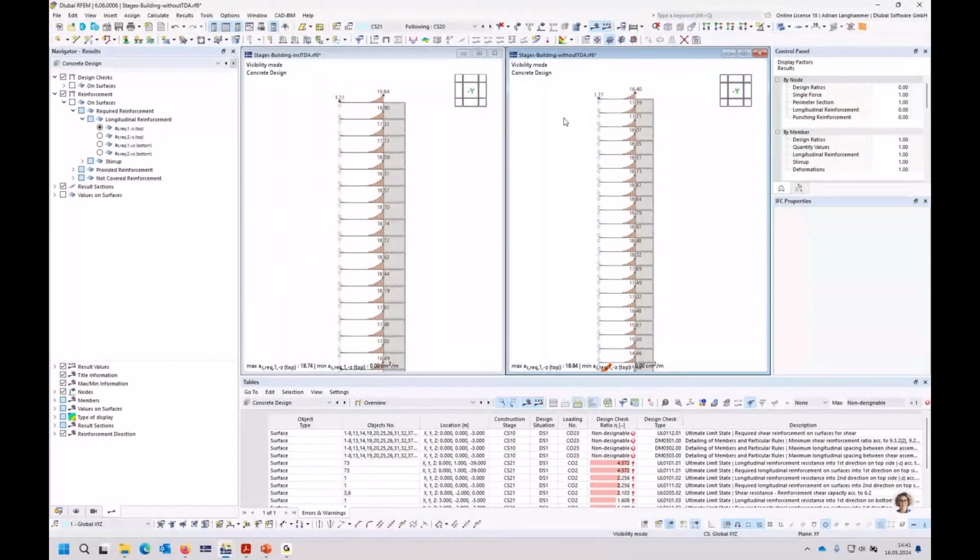There are structures, depending on how complex or how high these structures are and how long the construction process is, where you have an influence due to long-term behavior due to creeping, where there could be a redistribution of the internal forces, like shown for the first example. There was a quite significant change. Of course, it was due to the added support in the middle.